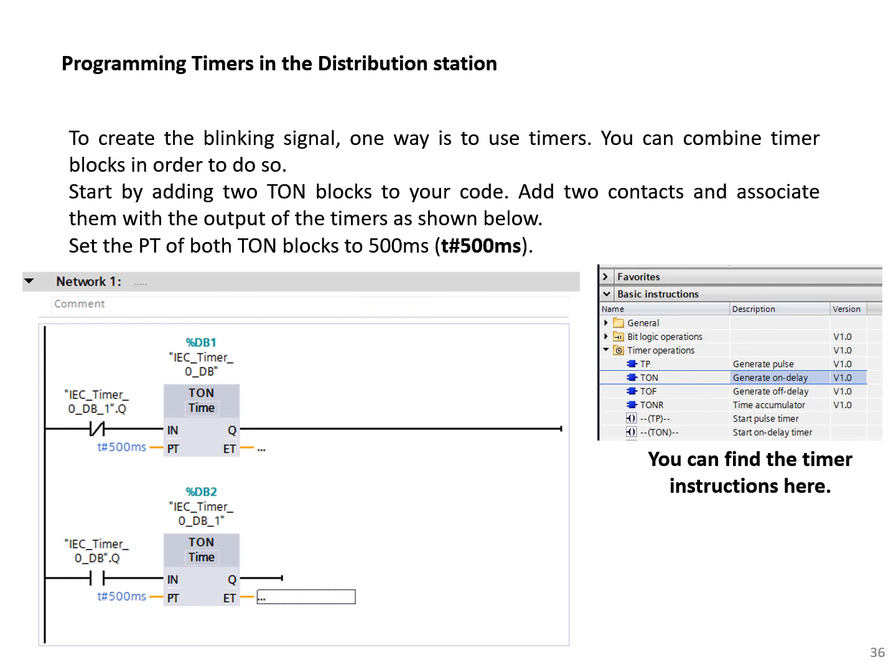Okay, these are default names for the timers, but you could change the name to whatever you wish. And here, if you start typing the name of the timer, then you could have access to the variables of the first timer, like the done bit or Q bit of the first timer.